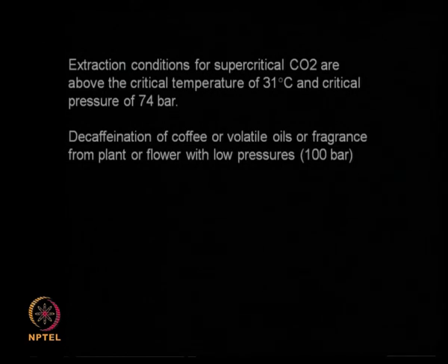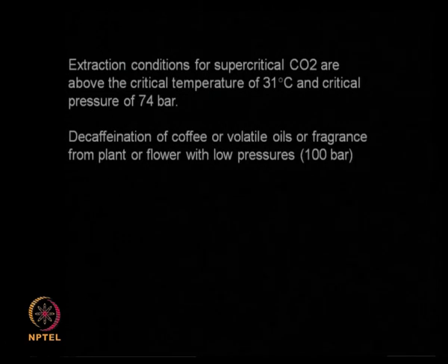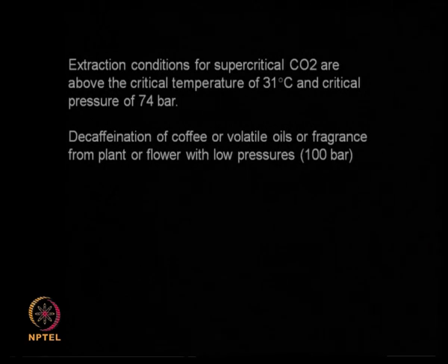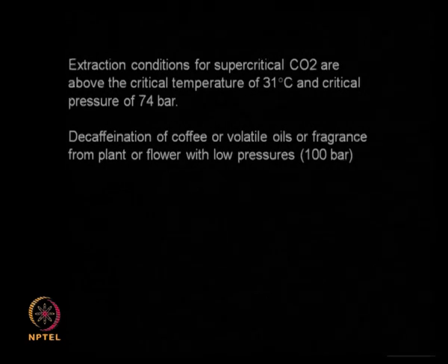For example, if I want to decaffeinate coffee, or if I want to extract volatile oils or fragrance from a plant or flower, 100 bar is enough. 100 bar is considered a low pressure. Okay, so at 100 bar and ambient temperature, I can remove the volatile oils and fragrance from flowers and plant material, because here you do not want to increase the temperature, otherwise the fragrant molecules will lose their activity. Similarly, I can decaffeinate coffee at such low pressures.